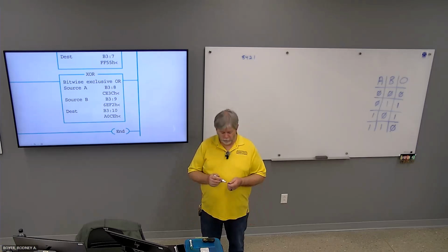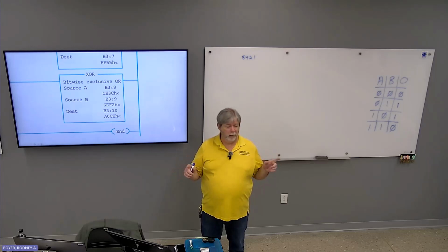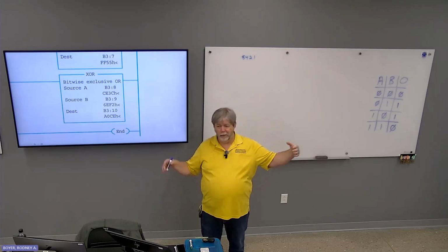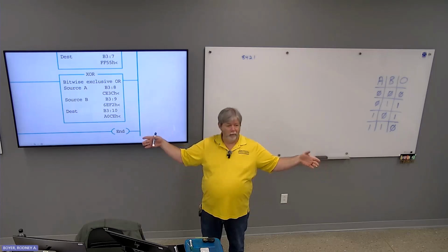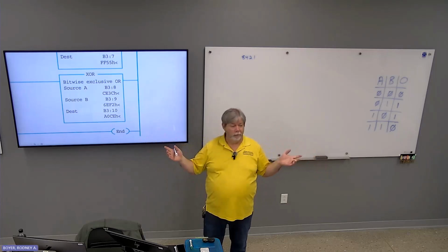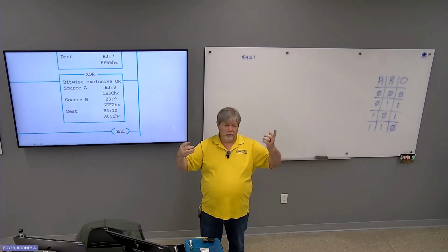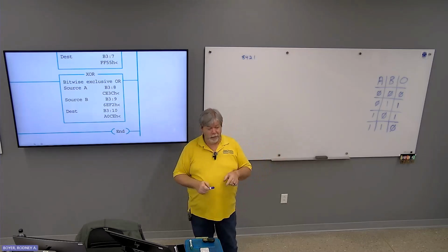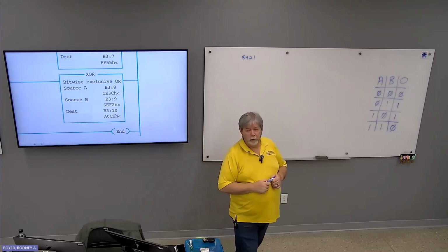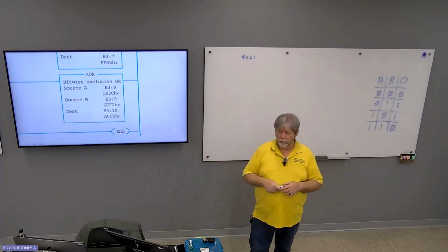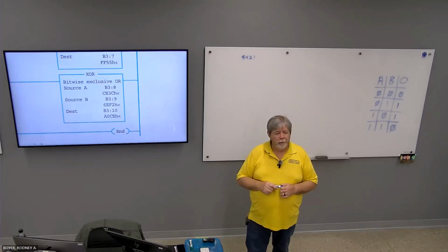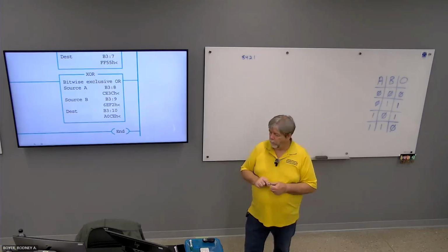Okay. Can you guys have a three-way switch set up in your house, you know, top and bottom of the stairs, different sides of a big room or whatever. That's an XOR. If both switches are up, the light is off. If both switches are down, the light is off. If it's one or the other, the light's on. Assuming the switches are installed correctly. If one of them's upside down, then, you know, that kind of goes out the window. Okay.